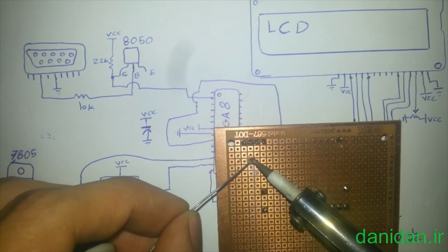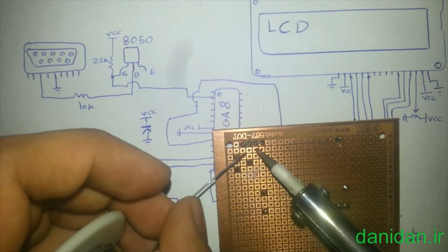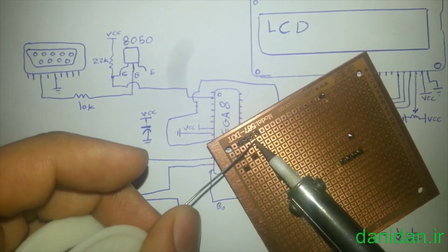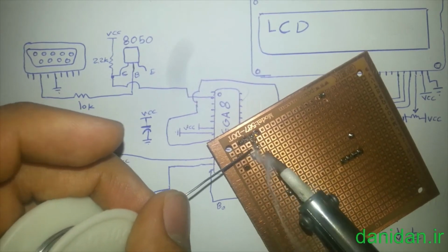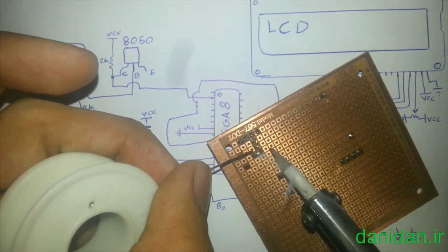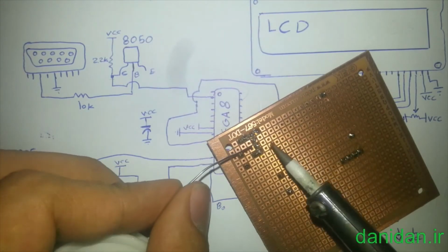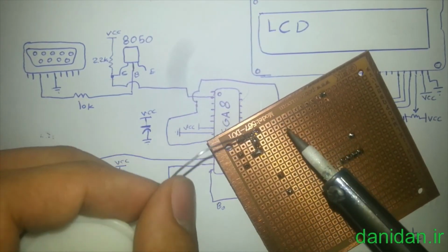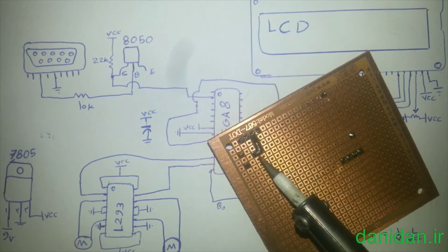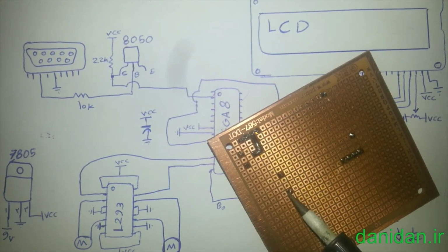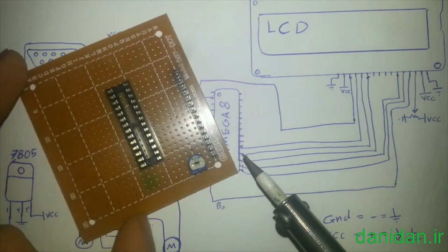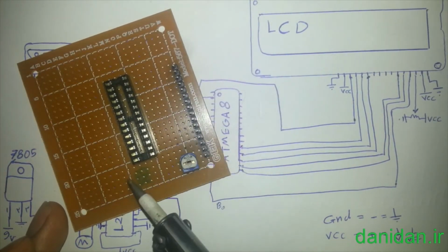Just be careful, you need to connect the middle pin of your potentiometer to the third pin of your LCD. So to connect them, do like I do. To connect each part of your dot board, when you are soldering each dot, just wait for a sec to make that part cool and then try to connect each part together.